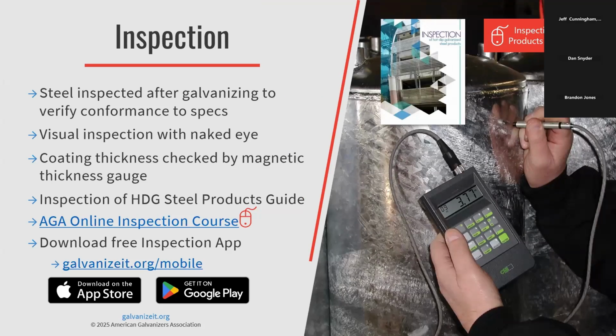All right, inspection. We have a wealth of information on inspection. A lot of times we have to go inspect the bridges that we build. So usually galvanizing is just conformance to specification for ASTM. Usually a visual inspection with the naked eye, just making sure there's no bare spots. Coating thickness can be checked by a magnetic thickness gauge. And then we have a ton of information.